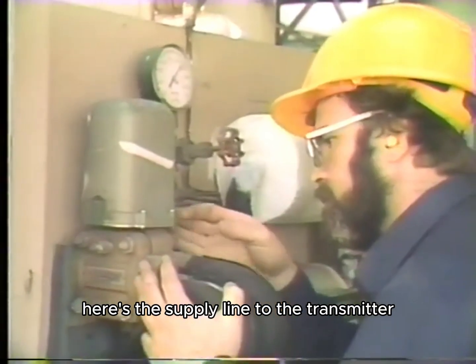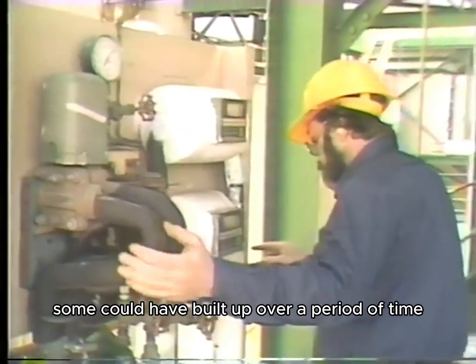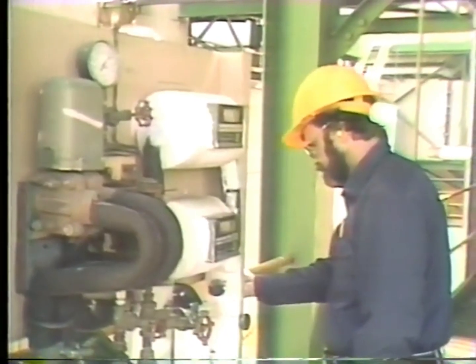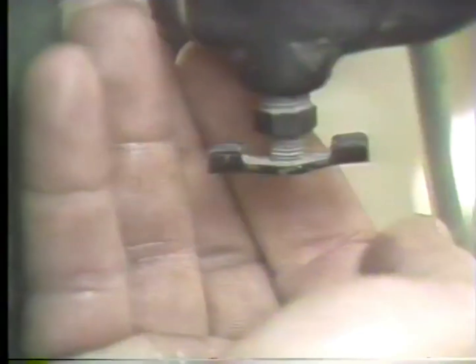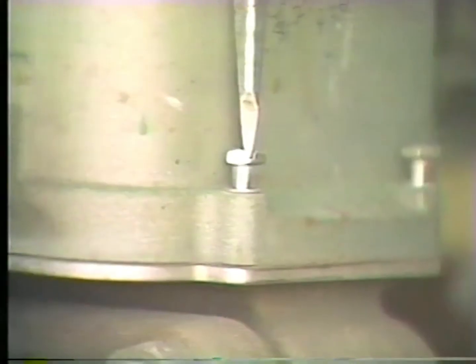Here's the supply line to the transmitter. I'll check the regulator to see if there's any moisture in it while I'm here. Some could have built up over a period of time. There's a little, but not enough to cause any problem. I'll take the cover off to see if anything is wrong inside.